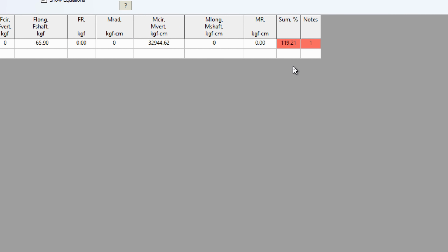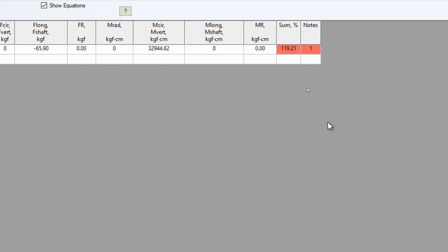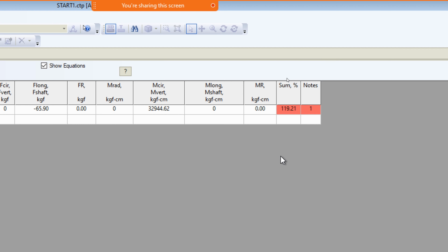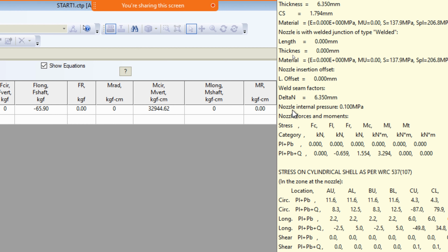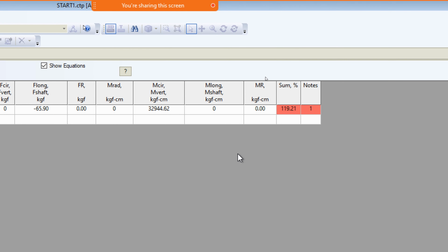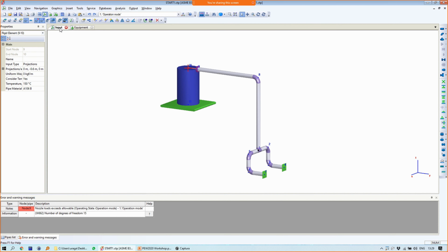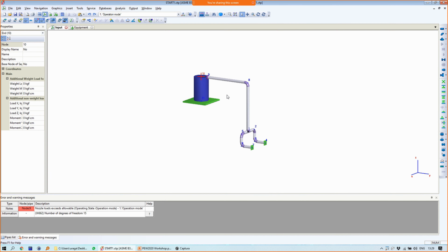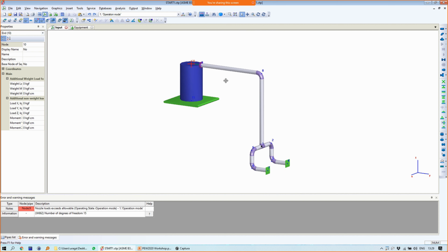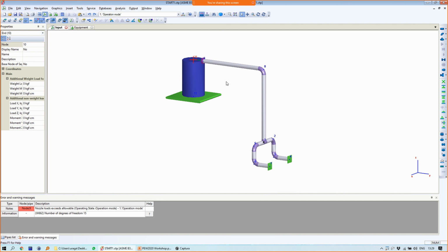Can we ask questions now? Yes, in between. I was just wondering, can you actually export this data to an FEA package? Let's say if you want to do simulation in ANSYS or Abaqus, where sometimes you need to do some corrosion or specific local damage analysis for fitness for service. Is it possible to export these models to an FEA package? We have a special converter to ANSYS. You can export the model to ANSYS.